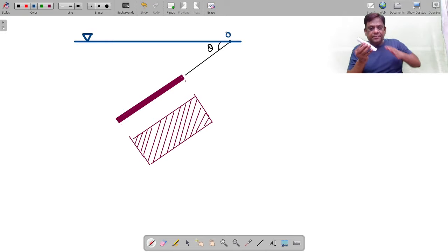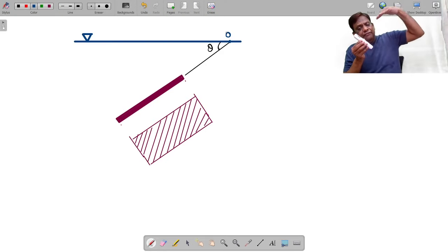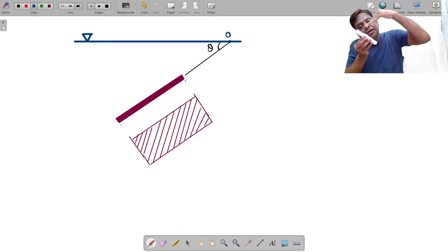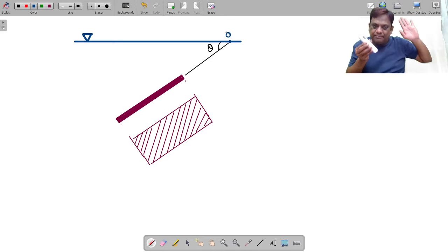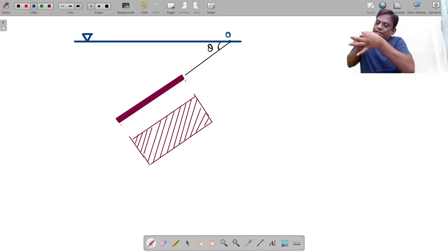There is an object. This side there is a fluid. So it is a static fluid. Whenever the fluid is static, the forces are pressure forces, that is, normal force only, because it's not flowing or moving. Therefore there is no shear. There will be only normal force, and normal force is nothing but pressure. On this we have shown this portion; if you see the other one, the force is coming on this area.